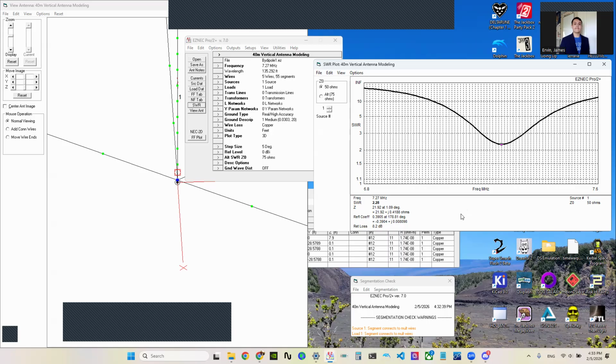What this might be is there's an inductor coil at the base, and they're using a series LC circuit, which you can think of as like an auto tap, right? So at a certain frequency of 70 centimeters on this handheld, there's an inductor and a capacitor here that is connected to one turn of the inductor that loads this thing. And at the resonant frequency, all the RF passes through this little series inductor capacitor and electrically shortens the coil by shorting out a bunch of turns. So that's how antennas like these work. They're not even remotely efficient, but they work. You just turn it on and it works well, right?